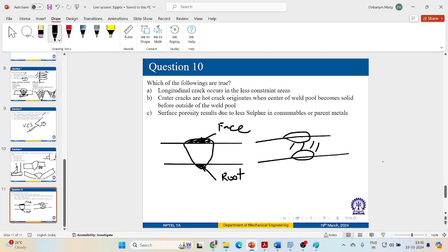So, yeah, there can be inclusions, like slag inclusion, where slag can be entrapped within the weld, mainly due to low welding current. There can be something called arc strike. Arc strike is generally some kind of localized coalescence of arc outside the weld region, right?